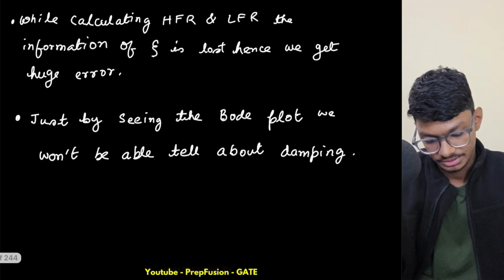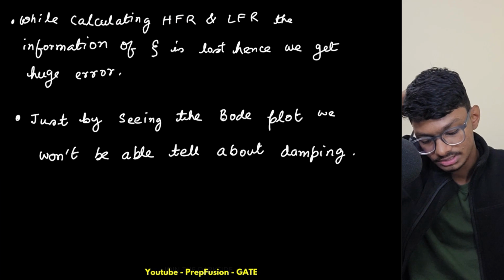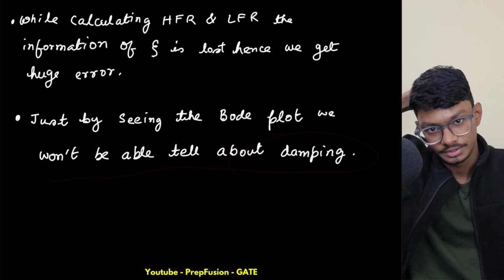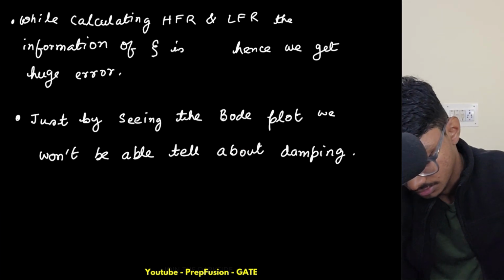Like I mentioned, while calculating the high frequency region, the information of zeta is lost, hence we get a huge error. Just by seeing the Bode plot, we won't be able to tell about damping. That is one more thing. Zeta is lost.